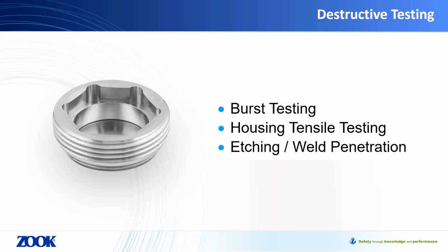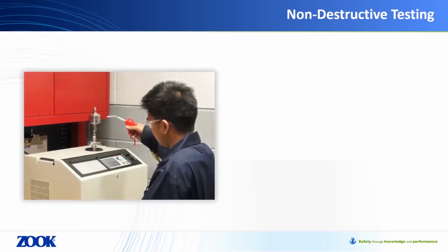While it is important to perform destructive testing on a shippable lot, there are various tests available to validate both weld parameters and product performance, which some or an entire lot of product may be subject to upon customer request. So let's look a little bit deeper at some of the non-destructive test methods that are commonplace in this product family. Many of the manufacturing and design codes surrounding rupture discs require pressure boundary components to undergo a proof test or a shell test prior to implementation in service or as part of supplying a code-compliant product.